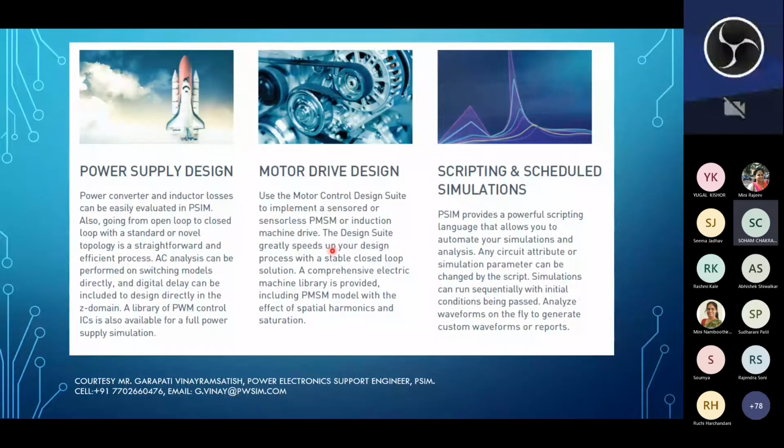You can use the motor control design suite to implement sensored or sensorless PMSM or induction machine drive, right? A comprehensive electric machine library is also provided in this, along with the effect of spatial harmonics and saturation. Similarly, scripting and scheduled simulations are also possible in case of PCM, right?